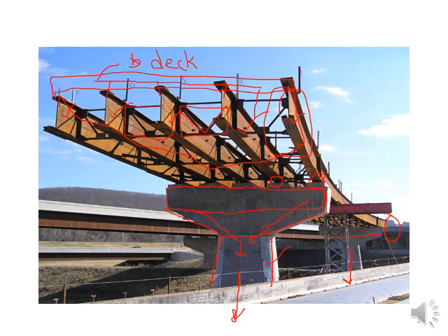That's why I have shared this picture with you, just to give you a better understanding of the steel girder bridge. What structural components are left to be discussed? Only the bridge deck and the steel girders. You can technically call all these girders stringers: 2 exterior stringers and 3 interior. The exterior girders are designed separately, I mean the load analysis is different compared to the interior.